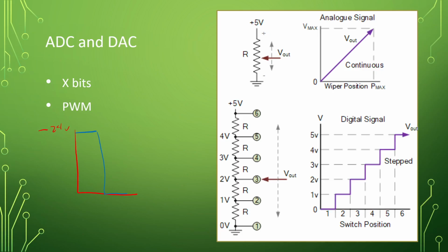Well, depending on when you're reading it, right? If you read it while it was on, it'd be 24 volts. If you read it while it was off, it would be 0 volts. Now, imagine you did that for a millisecond on and a millisecond off. 1 mil on, 1 mil off, repeating. All right? That's like you slamming the gas pedal, letting go of the gas pedal.